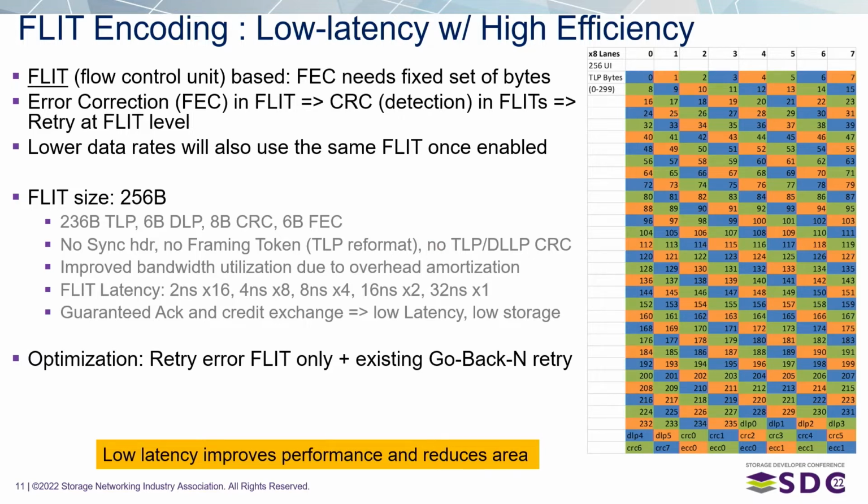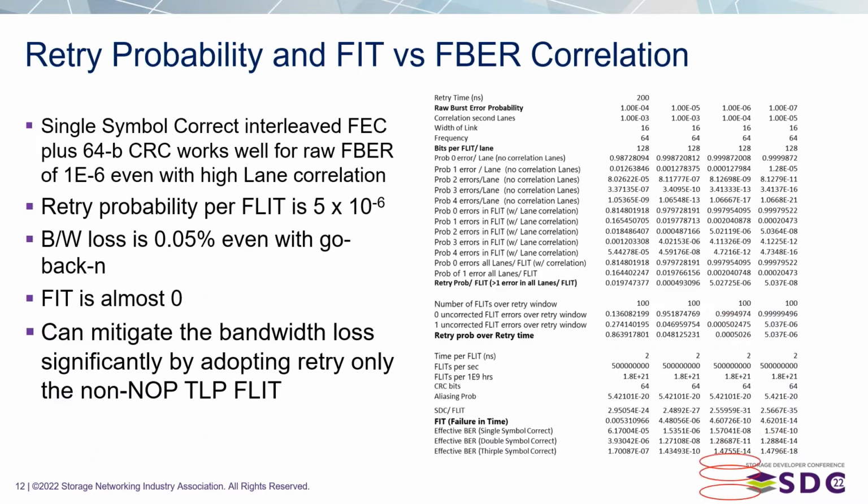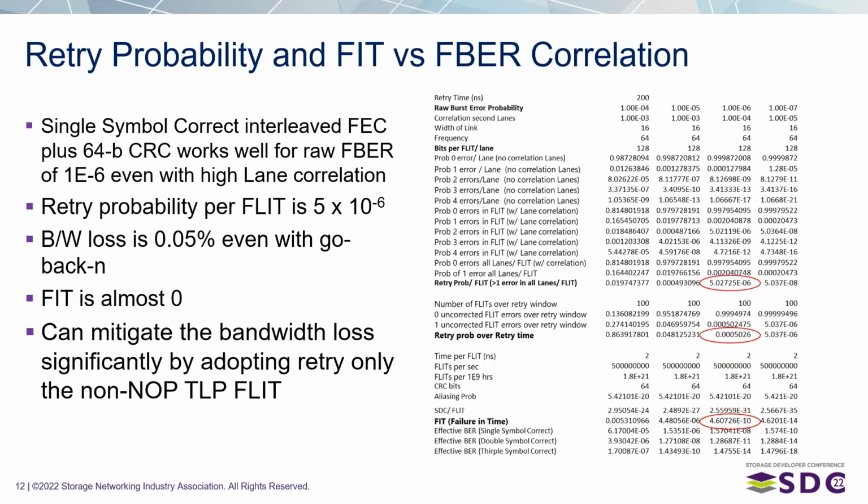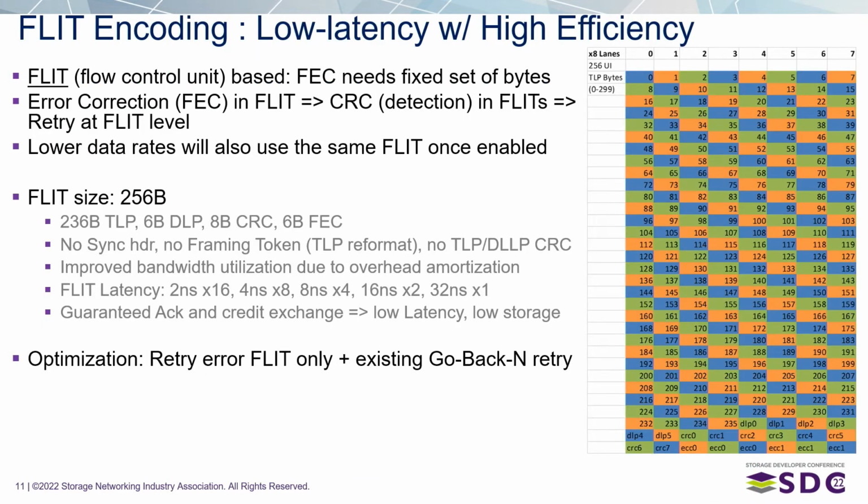And what happens is that you will notice that those 3 groups are these 3 colors. So what happens with those 3 colors is that each of them is a separate ECC group. So you will see that even if there is an error happening that goes across them, as long as that burst is less than 24 bits or 3 symbols long, 3 bytes long, you are going to be able to correct that error. All right. So that's the reason why we have done the arrangement in that particular way.